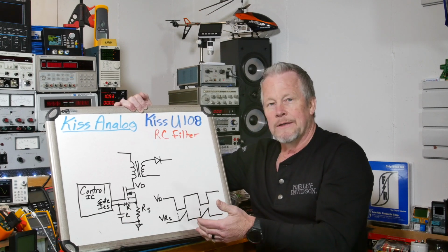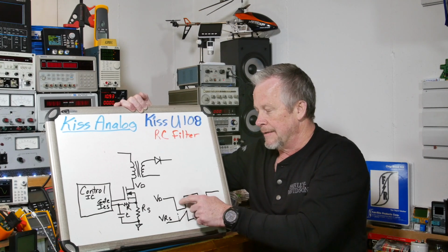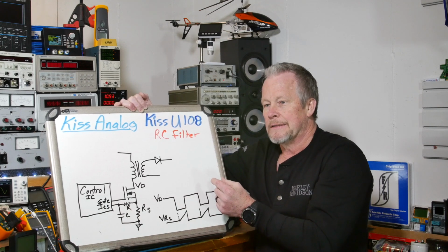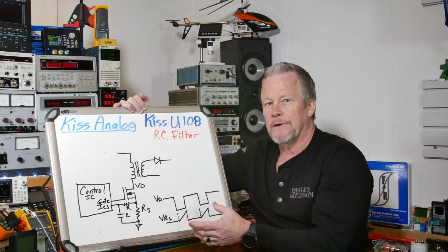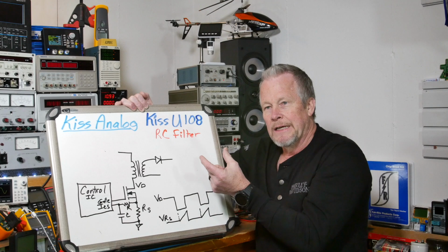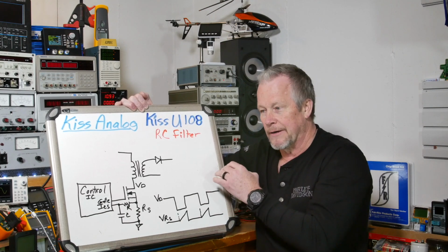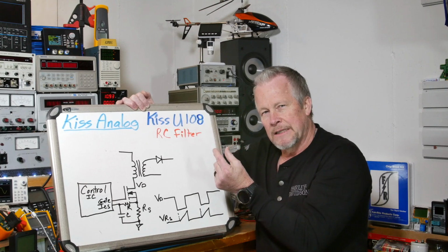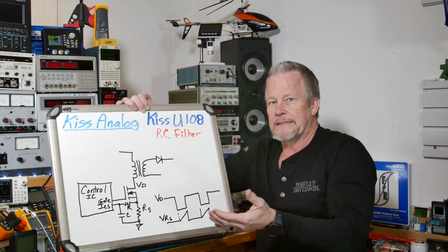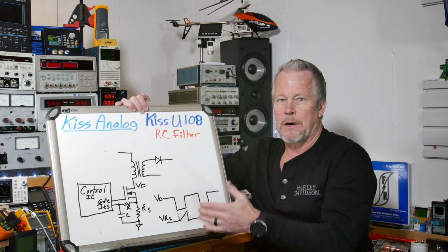Say you've made a time constant of 300 nanoseconds. Well, if your duty cycle starts closing in, trying to control the voltage, and the duty cycle is limiting itself down to 200 or 300 nanoseconds, then you're inside that filter, and now the filter is not giving the proper voltage feedback.